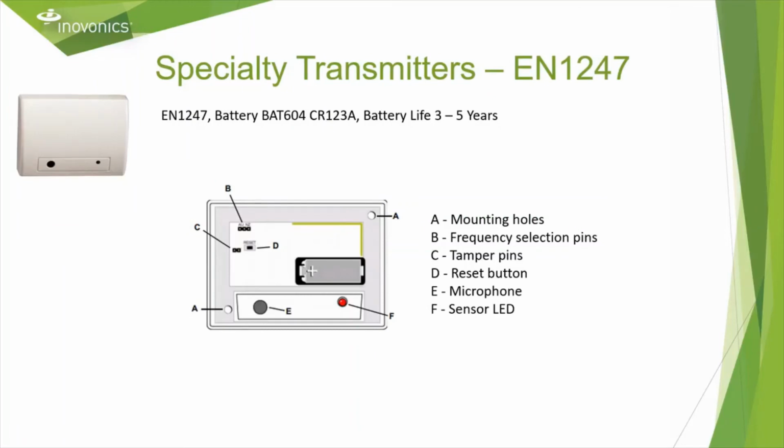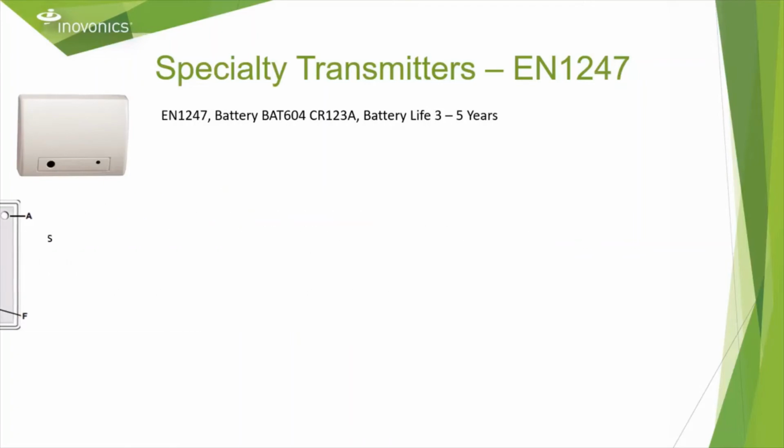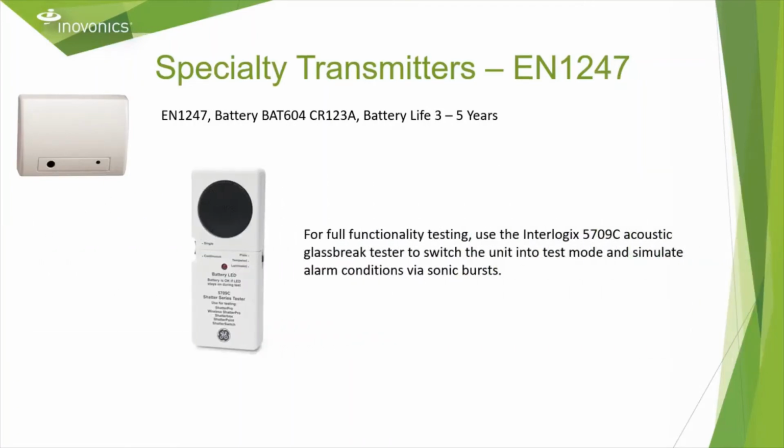Our glass break sensor uses a CR123A battery and has a 3 to 5 year battery life. The EN1247 can detect breaking glass from plate to tempered glass. To test the Inovonics EN1247 glass break sensor, you need to use the Interlogix 5709C acoustic glass break tester.